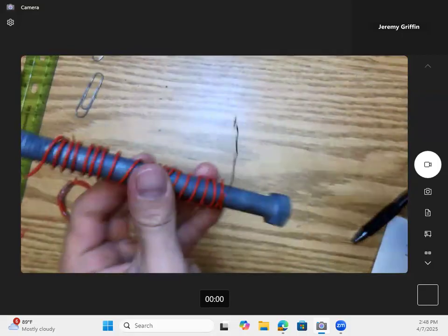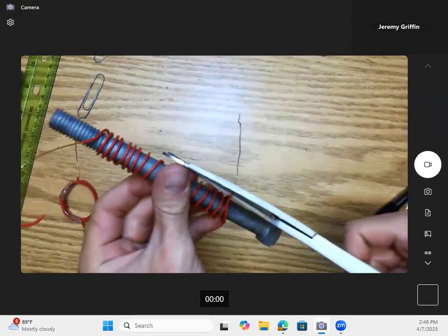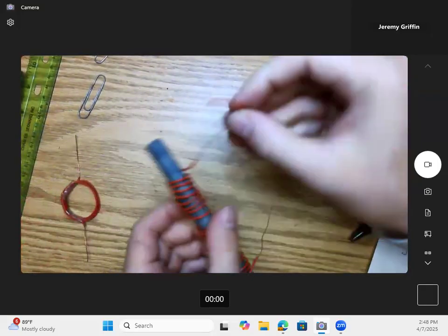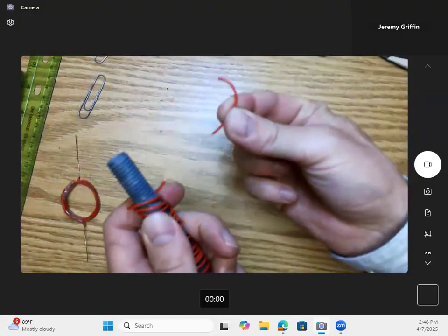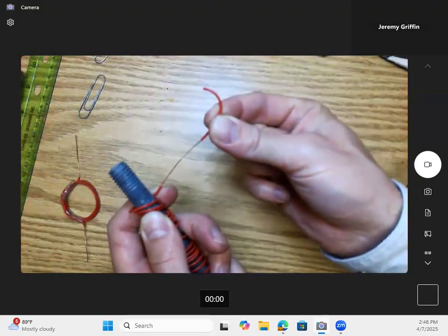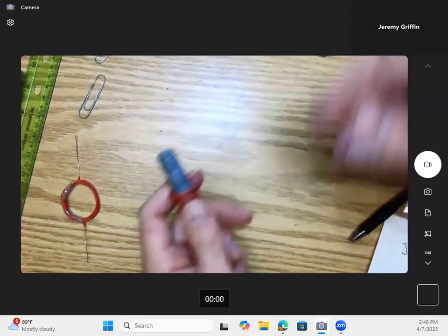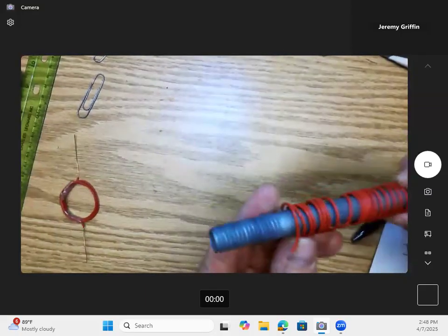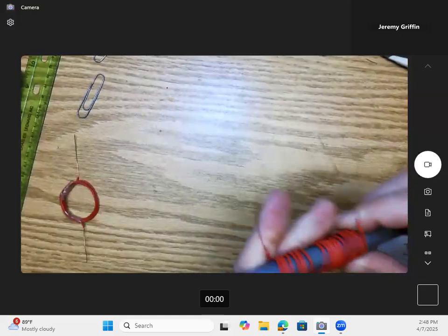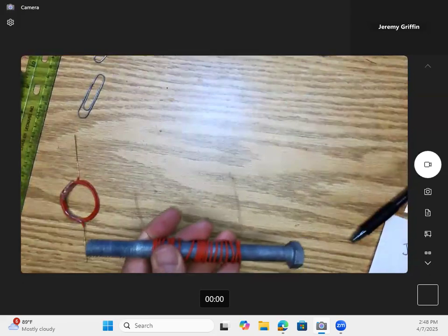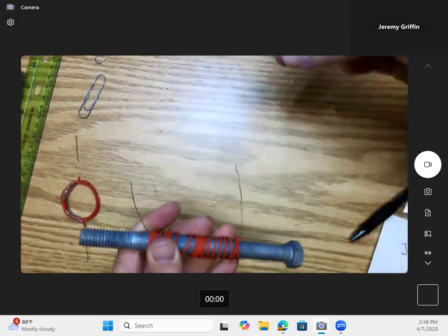So instead, the correct way to do this is to make a very careful incision. Go around, around, around, just cutting the insulation, not the wire itself. And then just pull this; it'll pull right off really easy. So that's the property that I'll probably show you guys tomorrow, also in case you have to strip any wires. So you just want to make a very careful incision, then put the scissors down. You're done with the scissors, and the insulation will just pull right off.